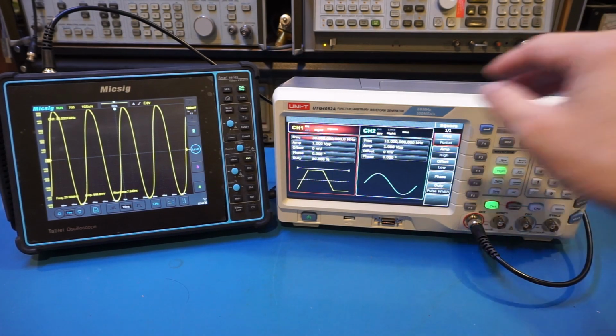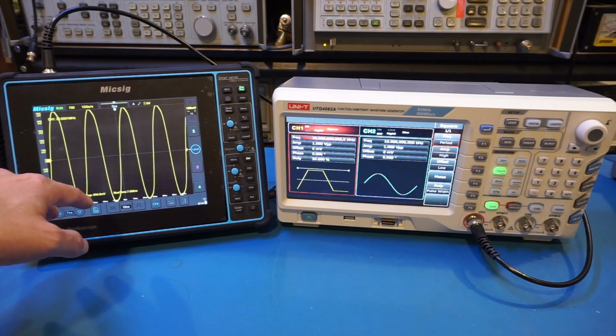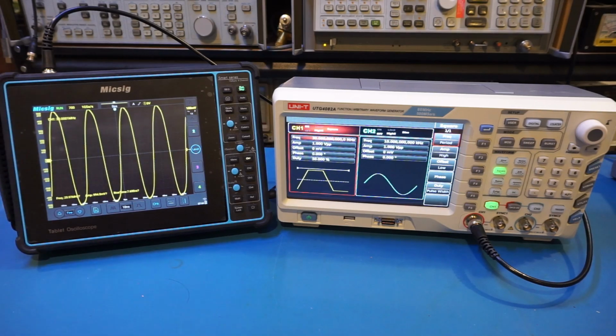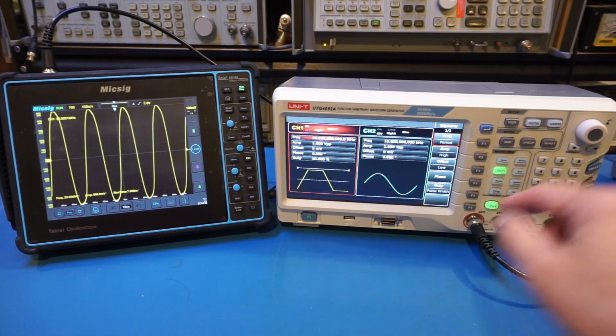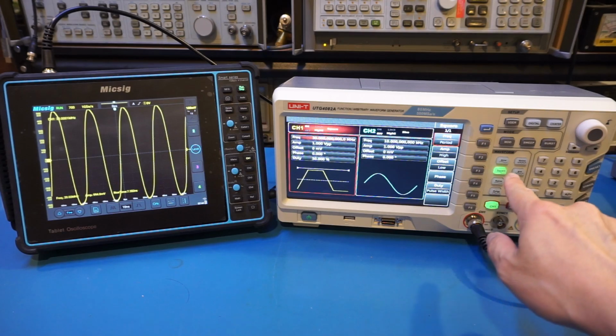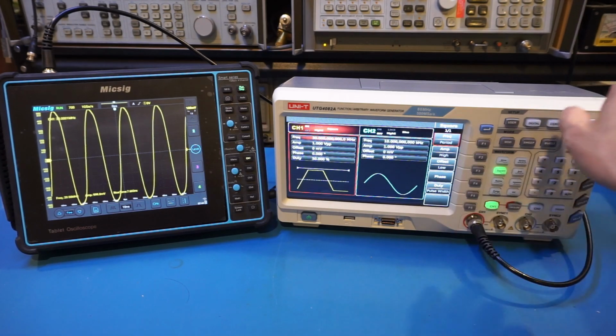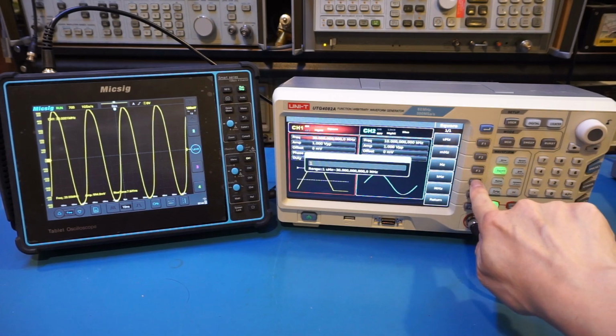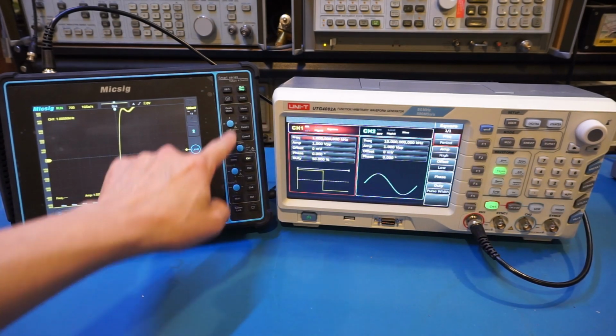Anyway, let's reduce the square wave frequency a little bit, because the square wave's rise time is not as fast, you do see this distortion here. So let's actually reduce the frequency to, say, 1 kilohertz. Let's do that. So the frequency, let's do 1 kilohertz, and let's acquire the signal.